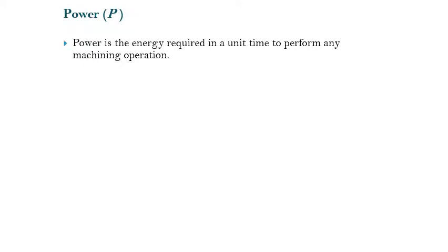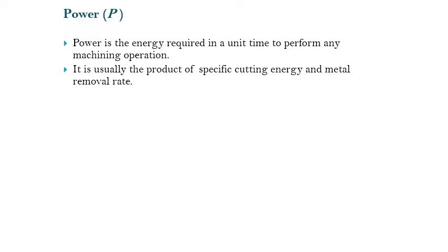So next, power. Power is very important. Power means the energy required in unit time to perform any machining operation. Power is usually the product of the specific cutting energy and the metal removal rate.